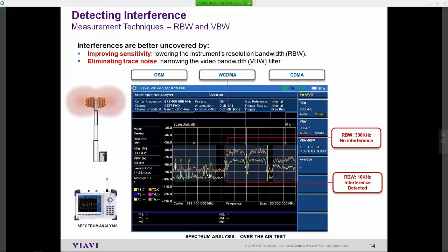I can share with you that I've been very uncomfortable over the years as I've witnessed many markets that have deployed UMTS and had GSM not only on the edges but often, as you can see right here, GSM signals placed right in between two UMTS carriers. For me, that is out of my comfort range, meaning I don't want to be encroaching too close onto other technologies.